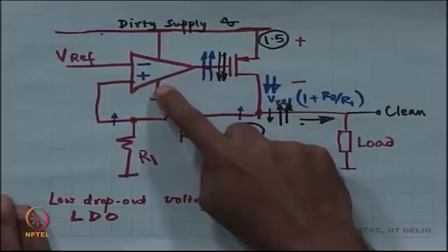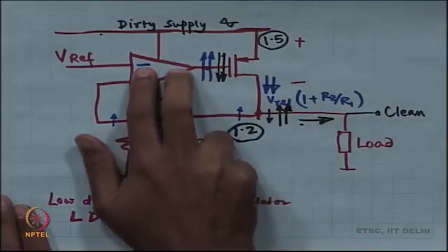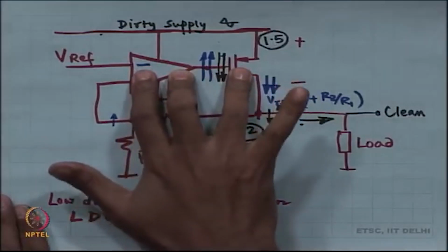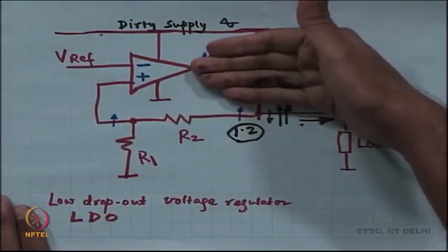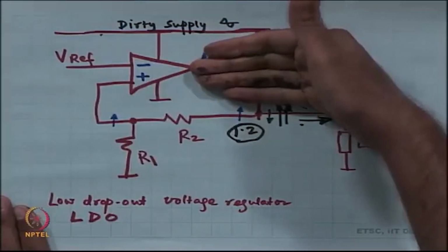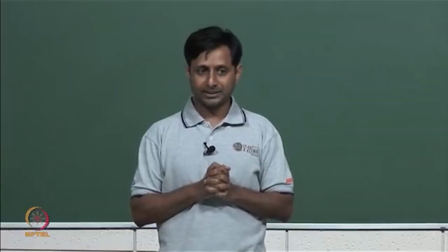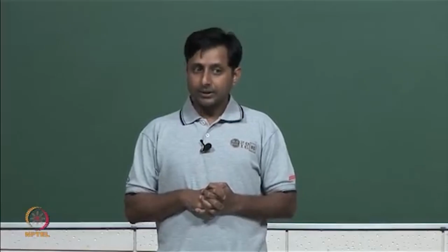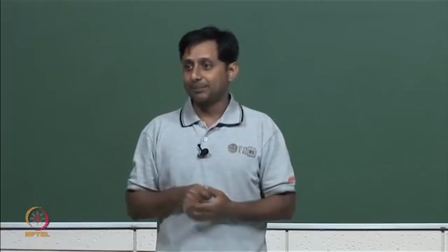When you do your compensation of this particular structure, it is going to be much harder because there are 2 poles in this plus one more pole, 3 poles. You can pull this third stage inside the op amp, and you can call that one gigantic op amp, which has 3 stages, 3 common source amplifiers back to back instead of 2. Now, you have to compensate for that 3 stage amplifier.